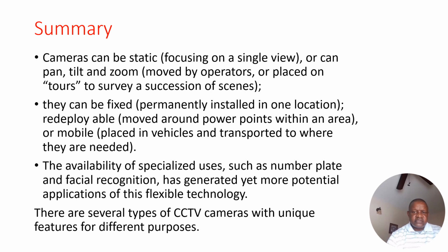you as a CCTV surveillance officer, take your time. Look at the cameras at your work area. Look at the cameras at your business area. Make clear conclusions. This is a fixed camera, or this is a PTZ camera. If it is a fixed camera, this is a bullet or a cube or a dome camera. If it is a PTZ camera, find out, is it manually operated by an operator, or is it automatically moving to capture scenes? It is very important for you as a CCTV surveillance officer to be able to identify these things and to speak the CCTV language.